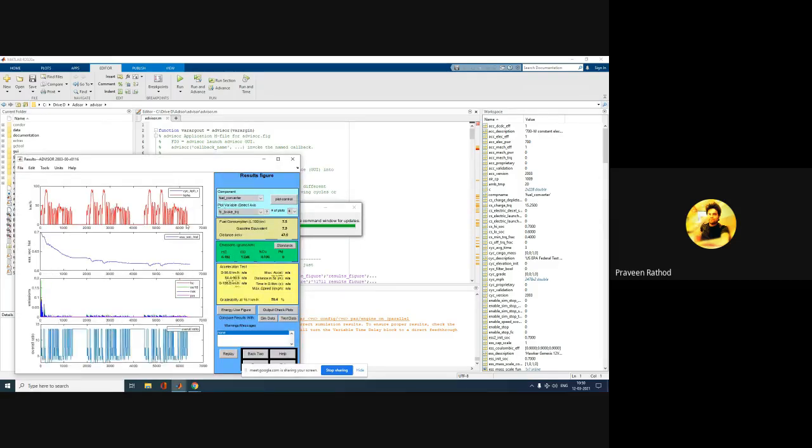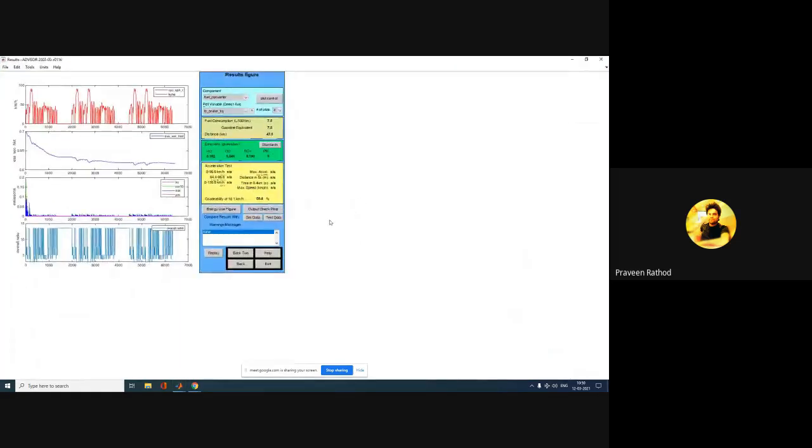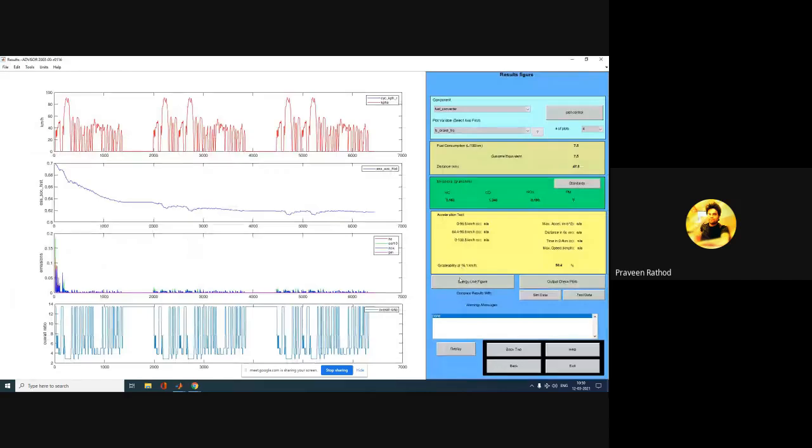Okay, it has been displayed. You can see we got, for 10 miles per hour, that is gradability at 16.1 kilometers per hour, around 50.4 percent grade value. We have not considered an acceleration test. Acceleration tests are written as not applicable. If you want to consider an acceleration test, you can consider that also, and you can get the values of all the acceleration parameters.